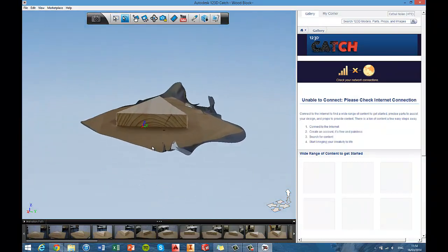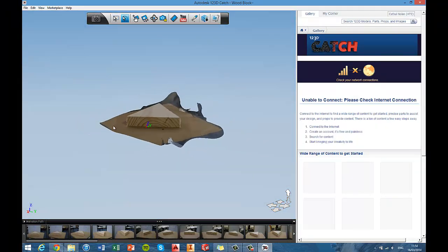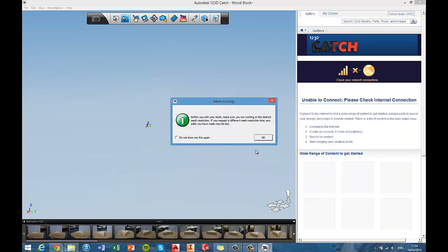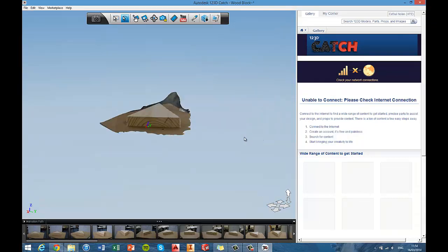The next thing to do is to remove any unwanted parts of the model, such as the tabletop. To do this, click the lasso selection on the toolbar and draw around the unwanted section. When it turns red, press delete to remove it. Do this until all unwanted parts are removed from the model.